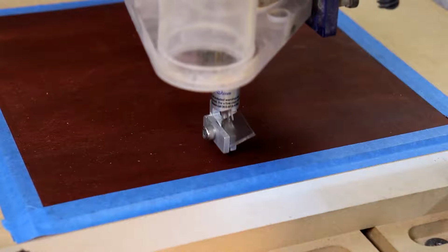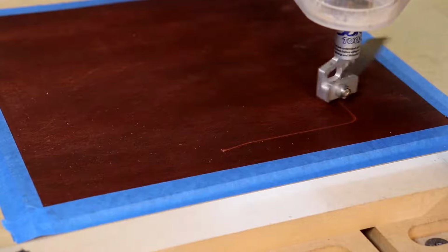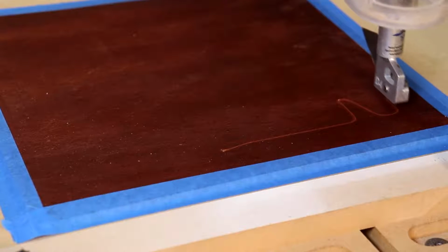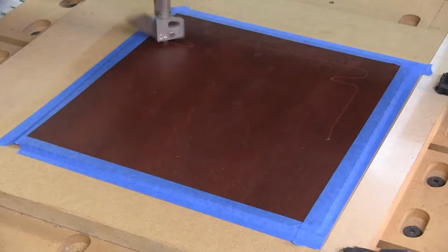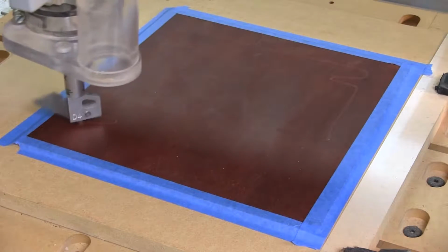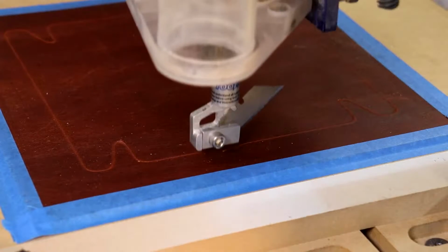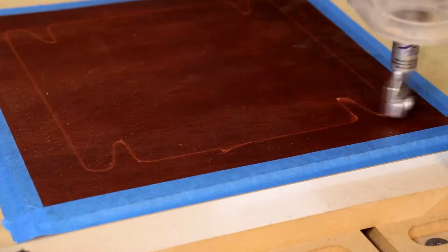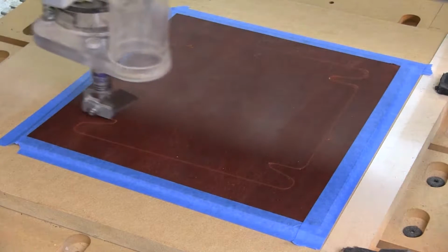Watch as the drag knife starts the cut. We're going to see a lead again right there. And then it starts pivoting through those relatively tight radii that this project has. I think it is so much fun to watch the drag knife do its thing on leather. Now again, I've sped the video up here. Real speed is 100 inches a minute. Fairly thick stuff, so I'm doing this in 2 passes, as we saw in the toolpath.